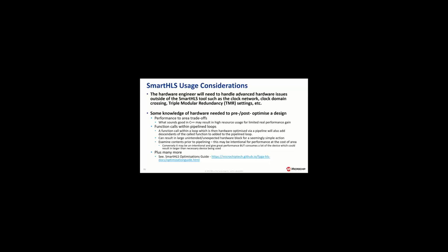As I said, it's not a replacement for hardware design, because what it won't know is explicit details of the hardware. It won't be able to do clock networks or clock domains in the part. It won't do triple module redundancy. It won't do all those fancy things that the hardware guys need to do to make things more robust. It's a conversion tool to look at the algorithm specifically. So there are bits where you're going to optimize it in, so some of those optimizations you'll still need to be looking at.